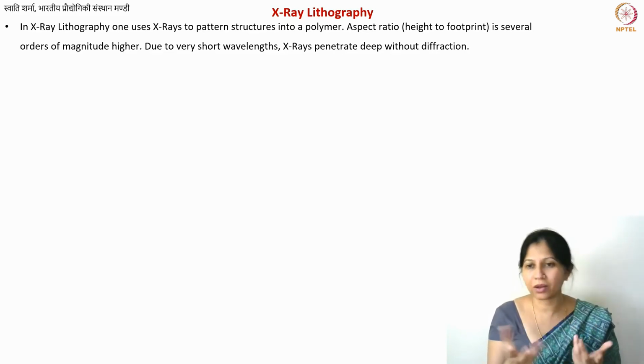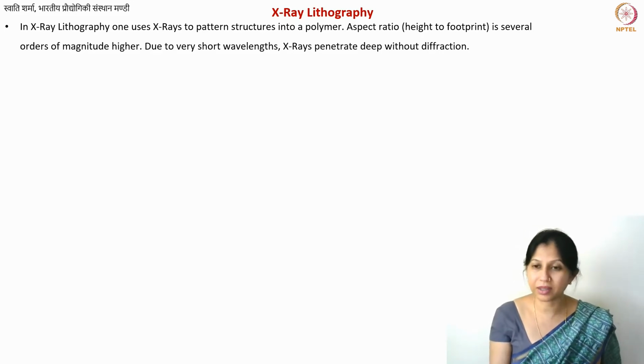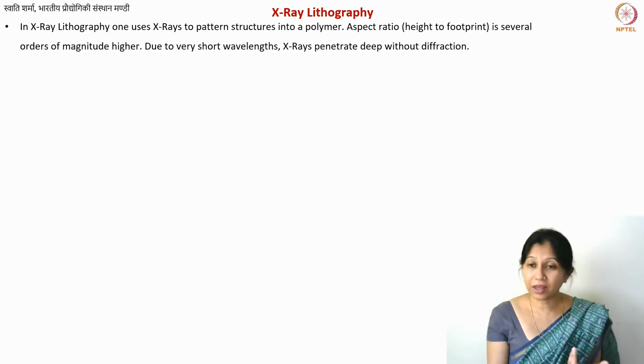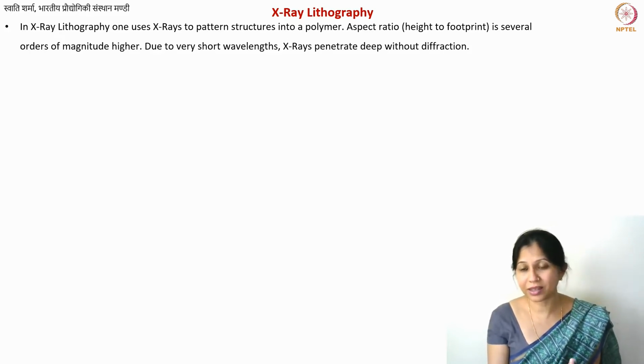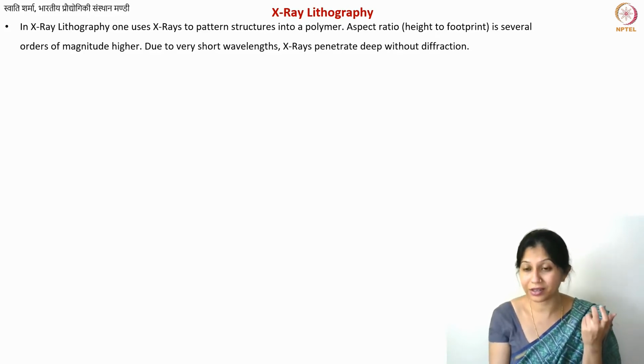What about the baking? That depends on the chemical that you're using, so the baking process and all that remains the same. Let's say the resist that you have is sensitive to X-rays now instead of UV light. But anyway, a lot of things are sensitive to X-rays, right? X-rays are higher energy electromagnetic radiation.